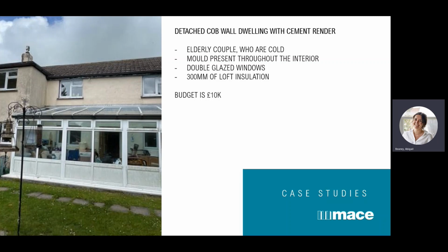So we would look at this, and we know that earth walls should be breathable, which means they're vapor open, moisture can travel inside and out, which is generally how older buildings were constructed, and ones with natural materials. So the fact that this has been retrofit with a cement render, which at one point was quite common practice, has stopped that performance happening. The water vapor can no longer travel in and out, and it's likely that the mold present throughout the interior is happening because of this.